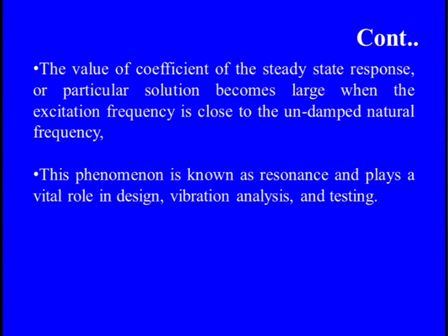It means that when the system is excited close to its natural frequency, we know that the particular solution is really significant at that time. This phenomenon, where the system is going towards its natural frequency, is known as resonance or the resonant concept, and it plays a real good role, because at that time a huge amount of energy is being exerted on the system. If we can control this part, given such huge exciting vibrations, or amplitude, this feature plays a vital role in the design, vibration analysis, or testing of any subject.